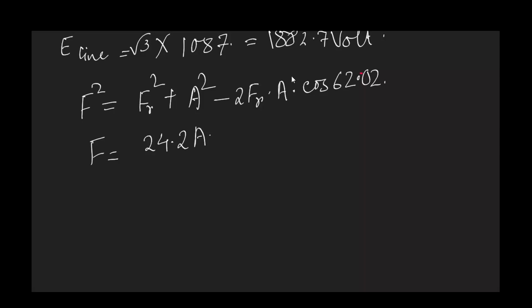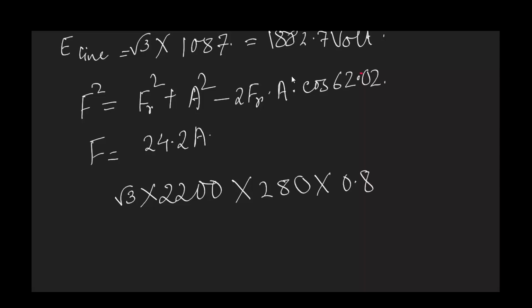So what is the input? Input is root 3 into our line voltage into our current into 0.8, our power factor as mentioned. What about our output?